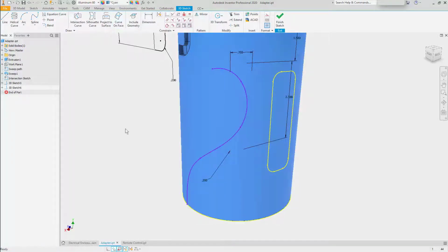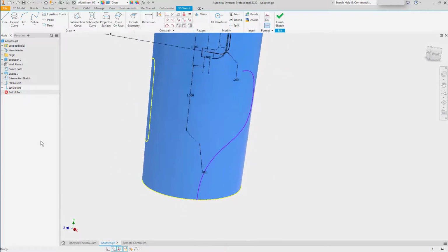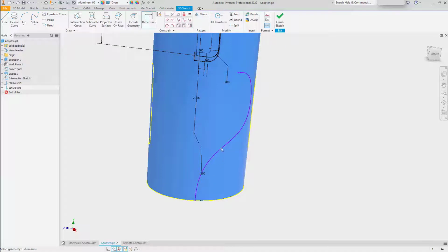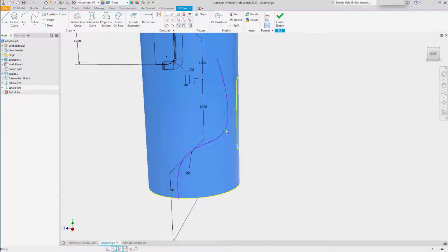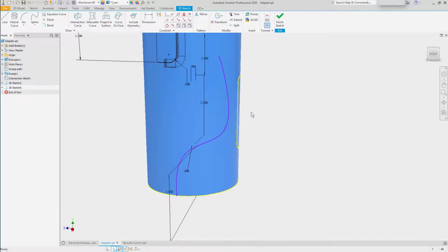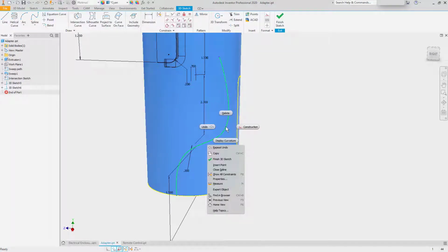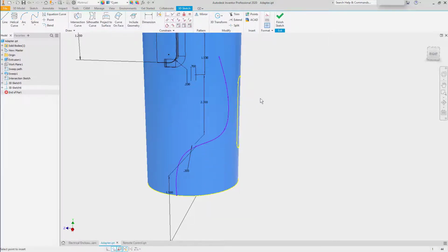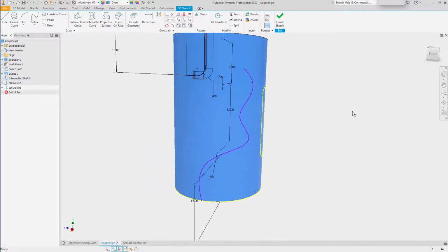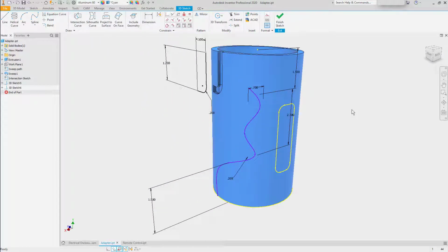There is some level of control available as well for being able to apply dimensions to locate the points. Any of the points that aren't completely constrained can be clicked and dragged to relocate. You can also fix a point as well. You can also add a point using Insert Point along the spline to add more detail. This is a great way to create complex shapes very quickly without having to create a 2D sketch to project.